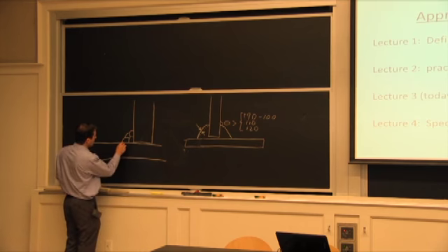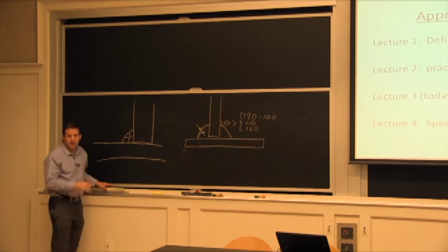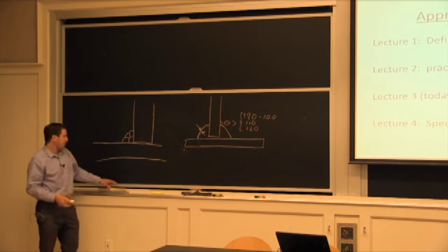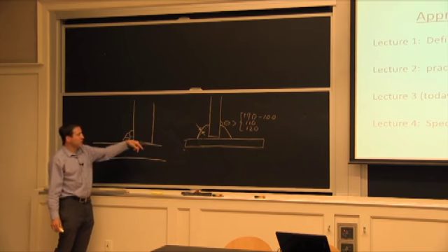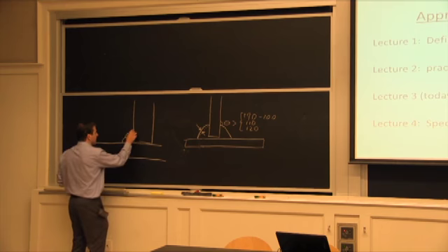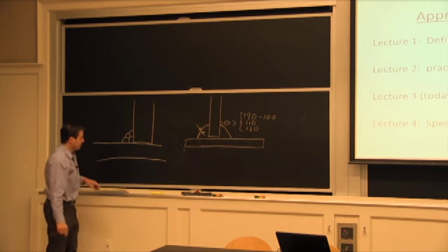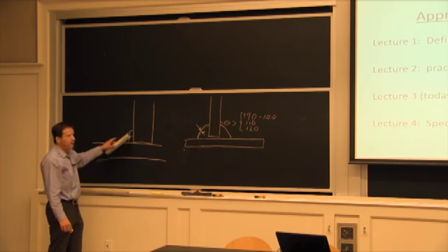But if you have something exactly like I drew that's actually pushing this way, that's also unacceptable by AWS. You can't have the weld with an angle less than 90 by AWS as well. But if you're exactly at 90, all you can do with AWS is use the criteria, the subjective criteria, that there's a lack of fusion.